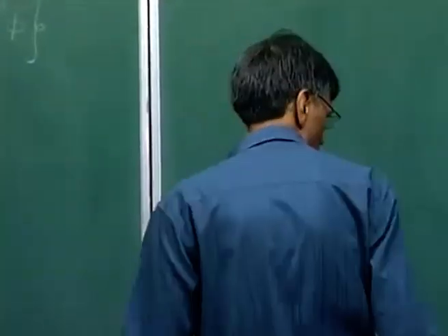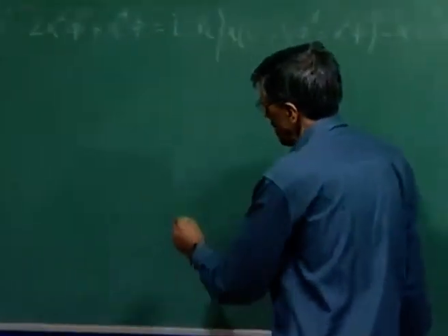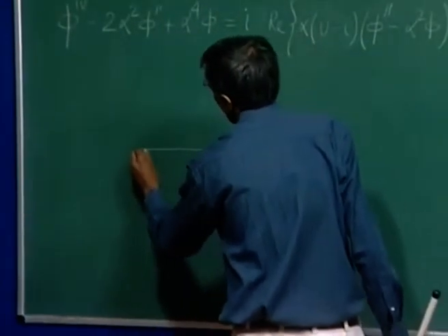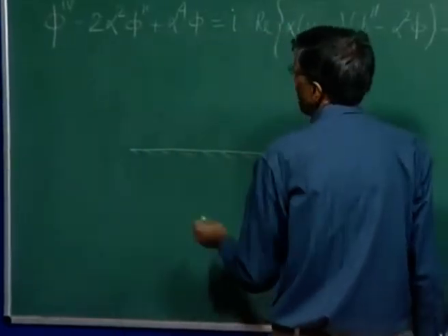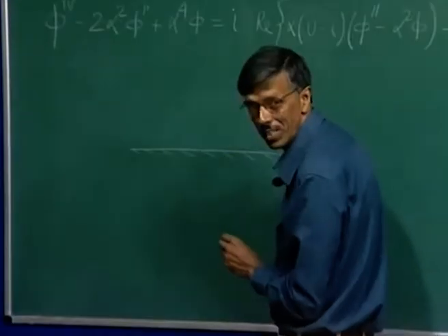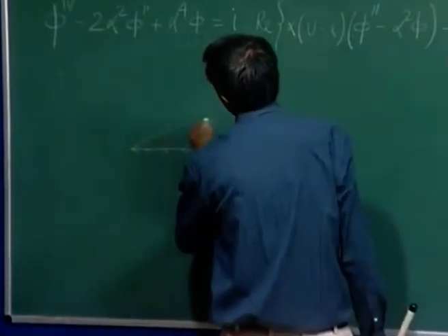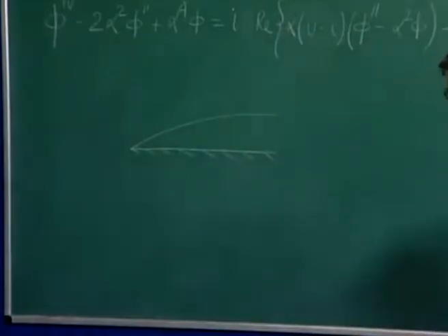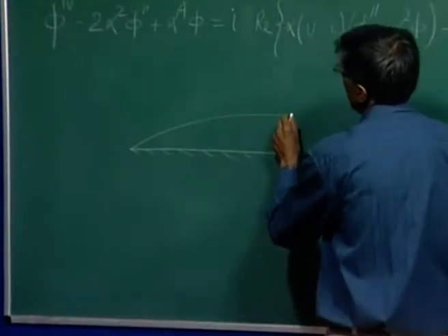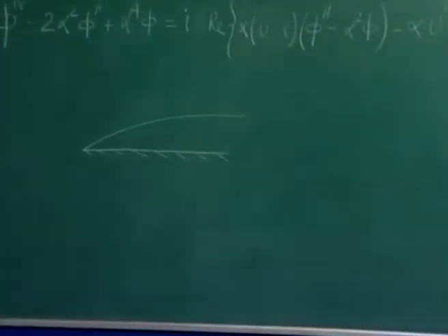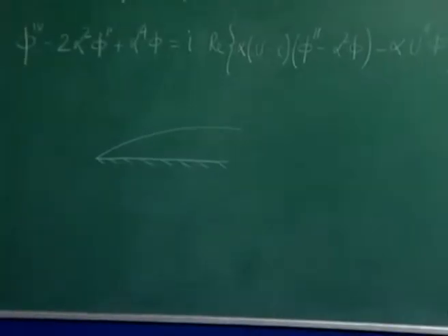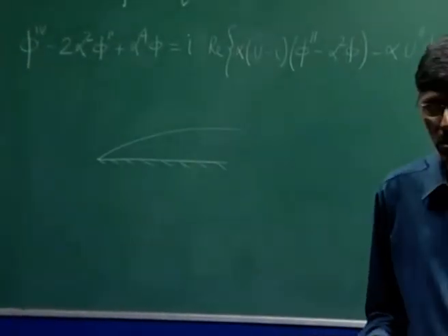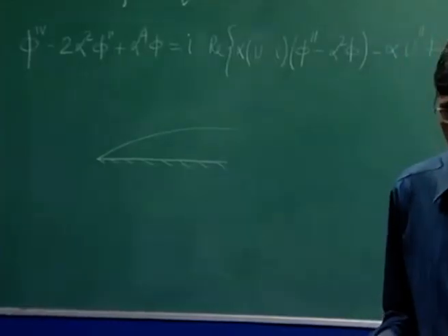Okay. So, if we look at the schematic a bit, this is how it should look: we have a flat plate here, over which a boundary layer develops. Since the flat plate has a very sharp leading edge, we will have a boundary layer originating from there. And now, what we want to do is make use of this Orr-Sommerfeld equation, and I would try to tell you how we got this. We got this because we made some vital assumptions. What was the prime assumption? That the flow is parallel.